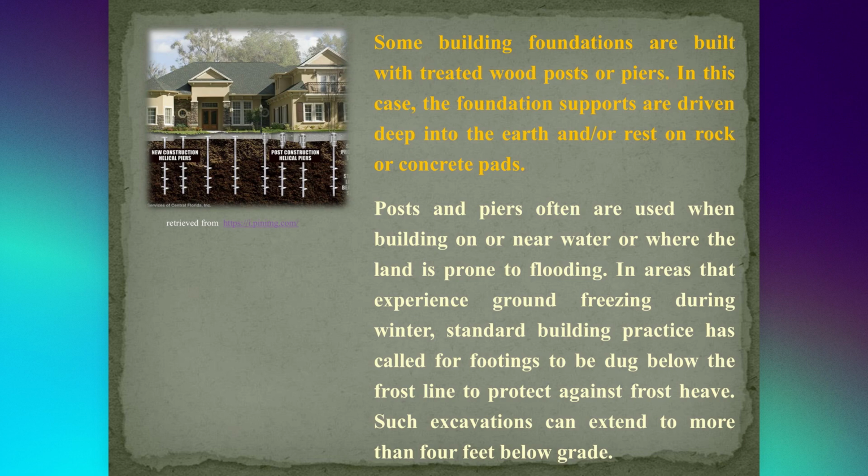In areas that experience ground freezing during winter, standard building practice has called for footings to be dug below the frost line to protect against frost heave. Such excavations can extend to more than 4 feet below grade.